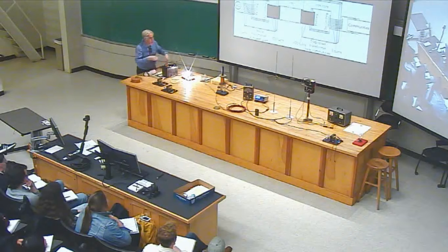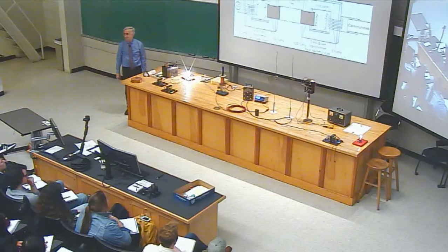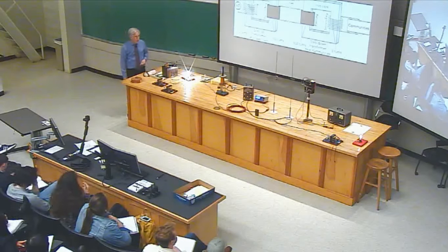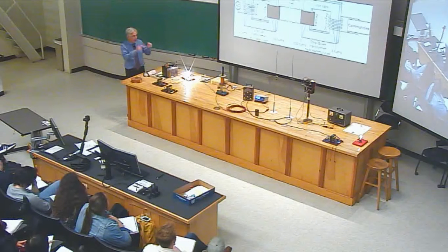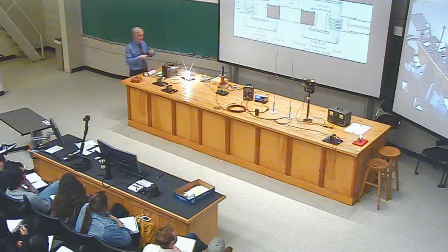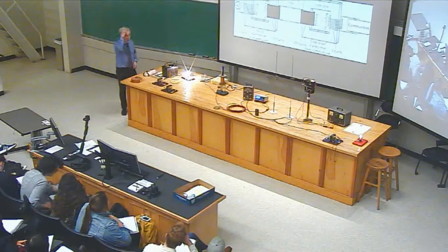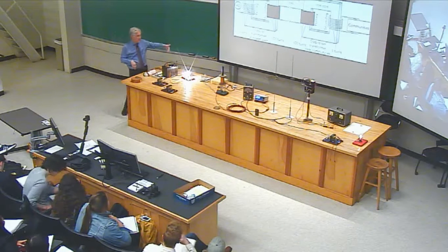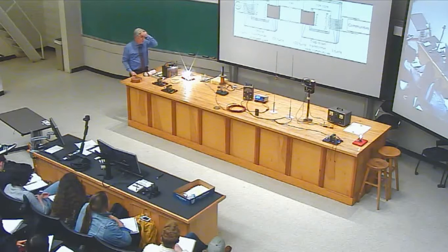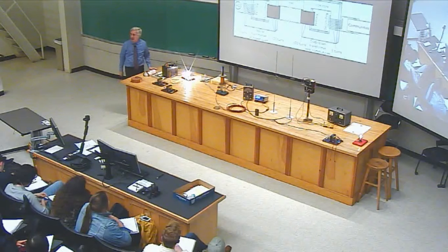The distant light bulb has a pretty measly glow there. The reason for that is because we're trying to convey power using a large current of charges that have a relatively small voltage drop available to them. Each charge doesn't have very much energy to drop off, so we end up needing a large current going through those very thin wires. They waste a lot of their power simply going through the wire, making the wire warm.